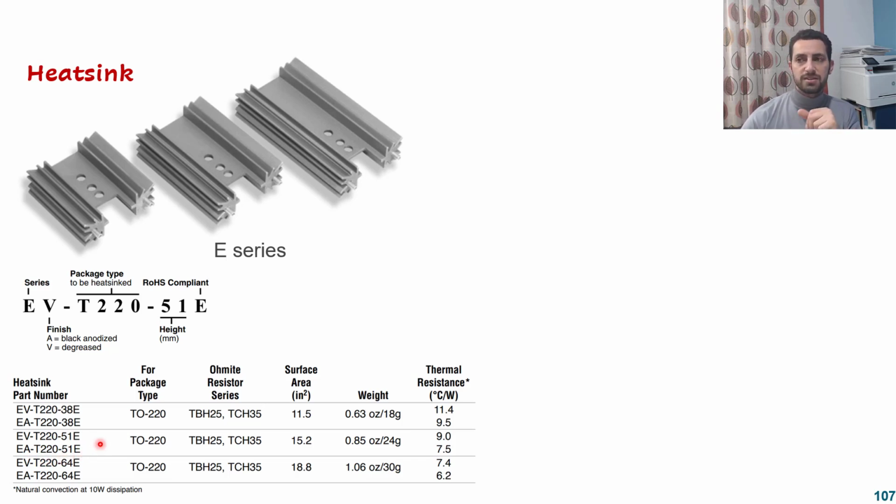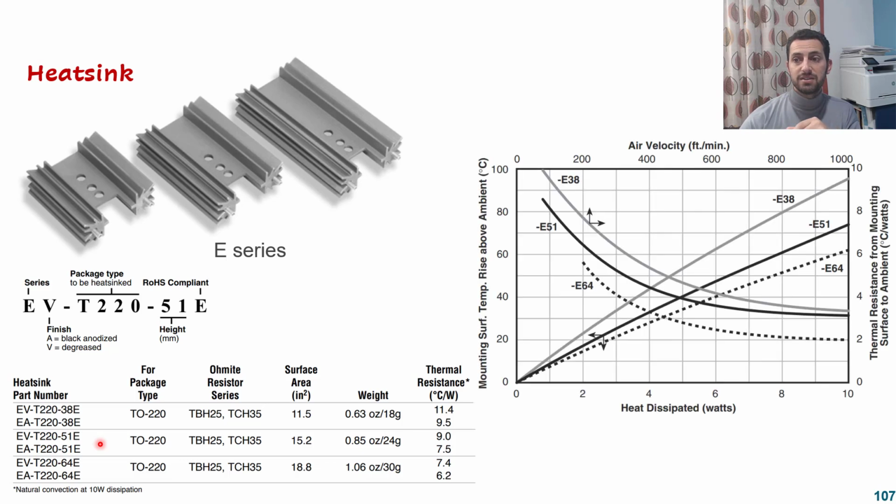If you go to this heatsink datasheet, you will find something like this, and this is very common between heatsinks. You have 4 axes, 2 horizontal and 2 vertical. The left side with the bottom side axis, those 2 go together, and you might find these arrows here. That means these 3 curves are read by this axis and that axis, and those 3 are considered if you are considering natural cooling.